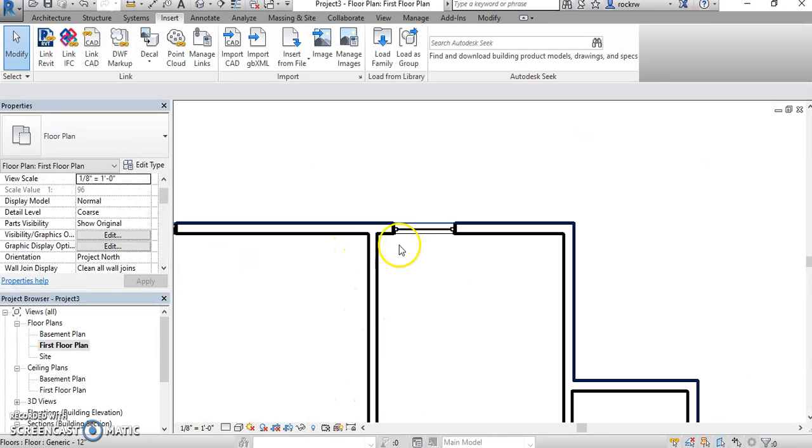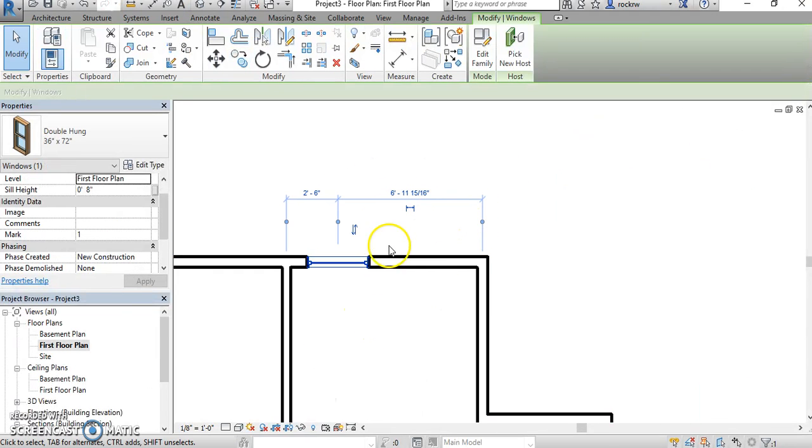Alright. So let's click on number 1, and these dimensions again present themselves. I'll click this dot to get it to go to the exterior, and I'll click this dot to get it to go to the edge of the window, and that dimension was 5'3", and it moves the window right into place. Oh, I'm sorry, my mistake. It was 5'3" to the center line of the window. So as you can see, I just moved these locations around, and I'll enter the text here, 5'3".